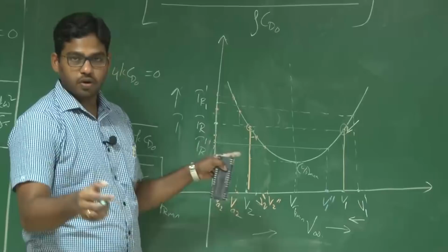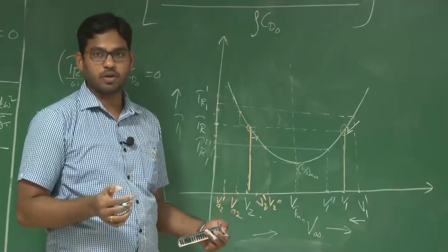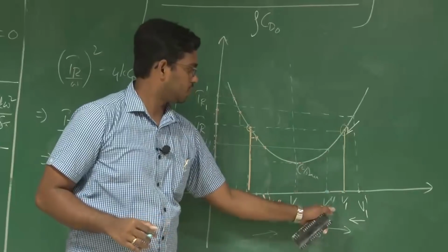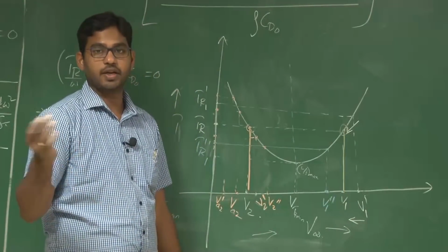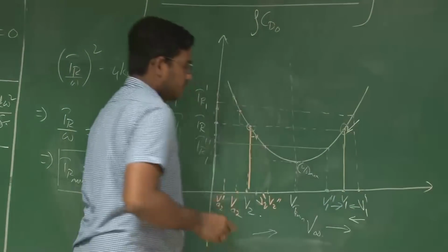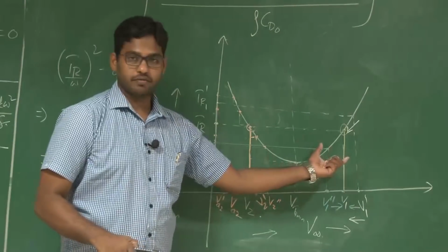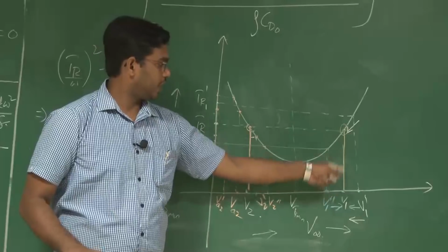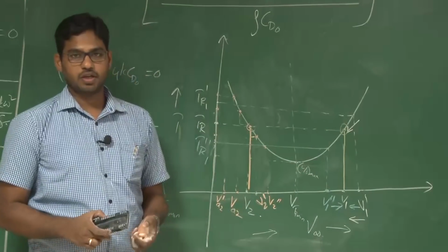Since you are not touching the throttle again, this additional thrust that is available will accelerate the system to the trim velocity or the earlier equilibrium velocity. That means without any external control, if there is any disturbance, if you are flying at this point, the aircraft will automatically come back towards its equilibrium.